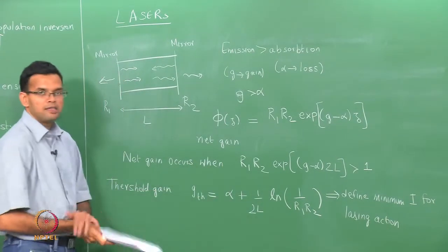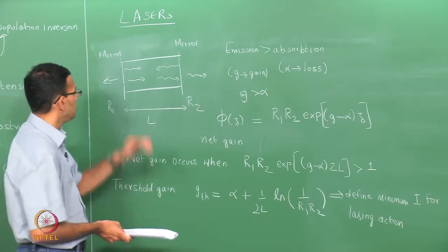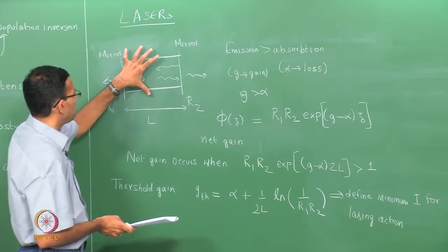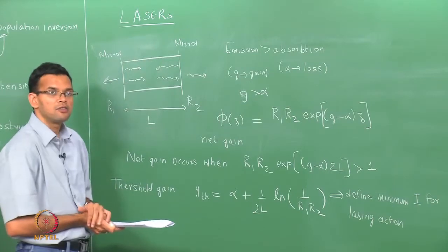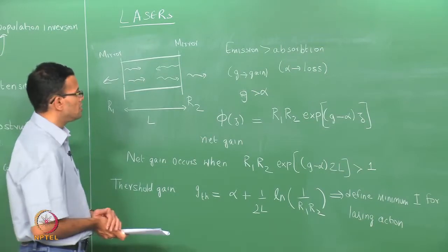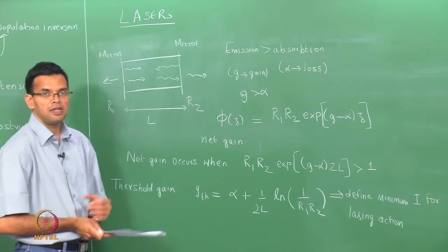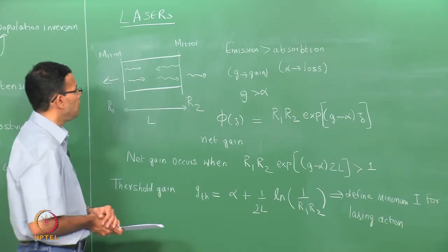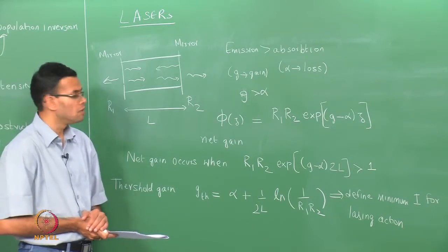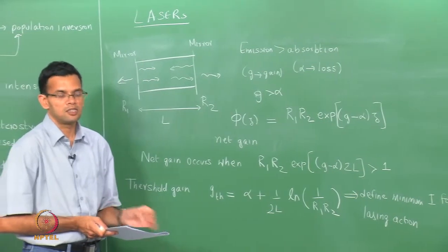So, in this particular example, the two reflectors help to confine the laser in the plane of the device, but we also need to confine the light within the active layer, so that light does not escape from the top or the bottom. This is done by usually choosing a graded structure with different refractive indices, so that you have total internal reflection and the light is kept within the active region. So, let me include that as well and draw a schematic of the laser structure.